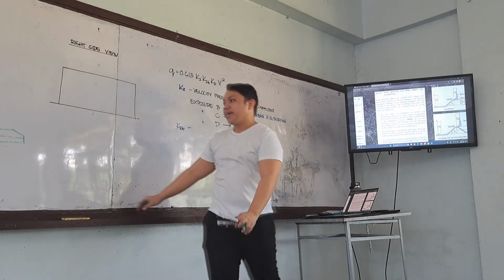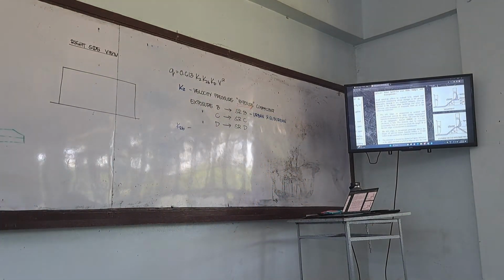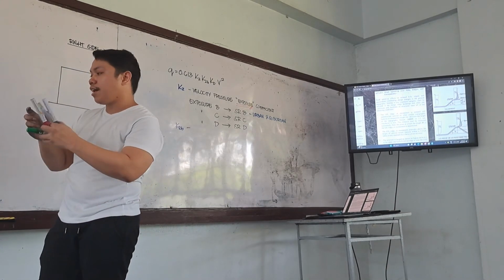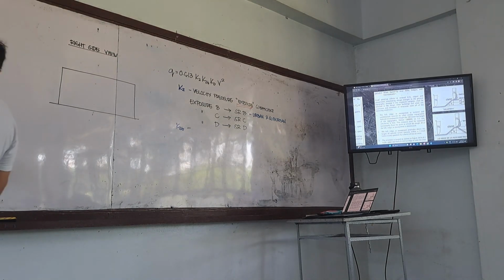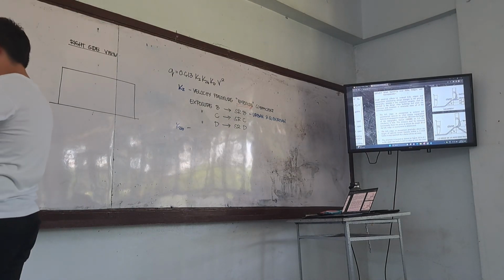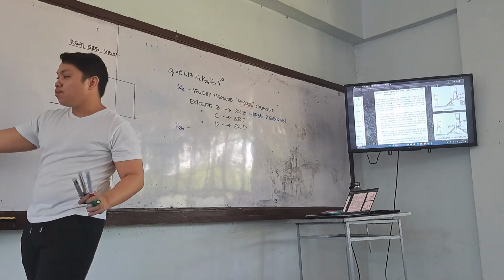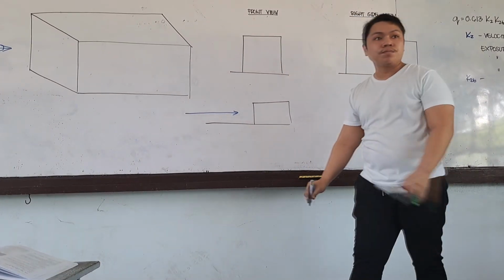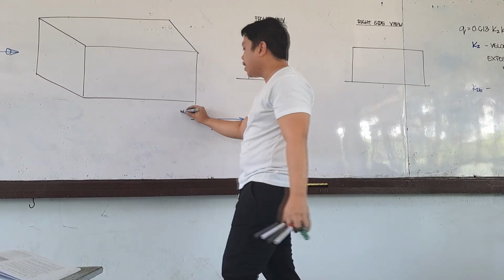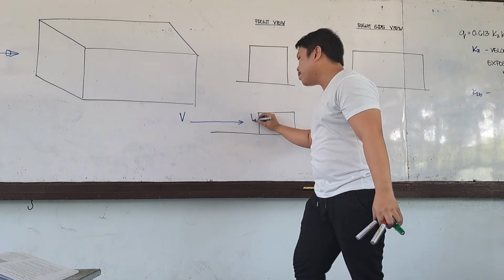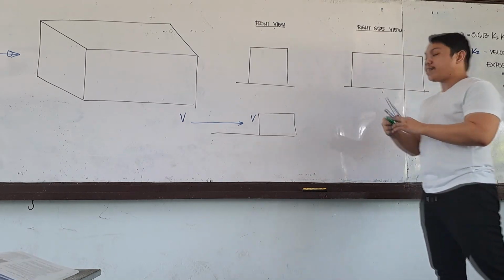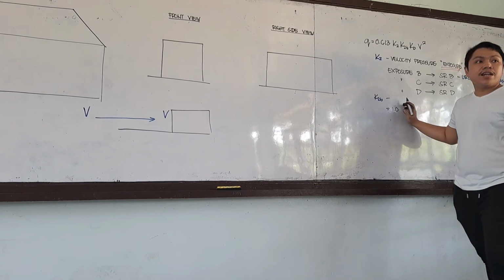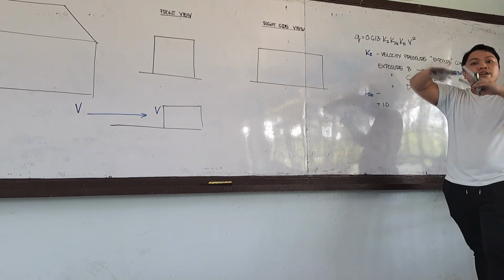Actually, for your building, what matters is whether it is located on flatlands or grasslands. If this is your building and your surface is flat, then when the wind blows there is no magnification. Thus, the wind V that reaches your building is just V. That's why most of the time, the value of our KZT is equal to 1. We rarely design buildings on high topography.